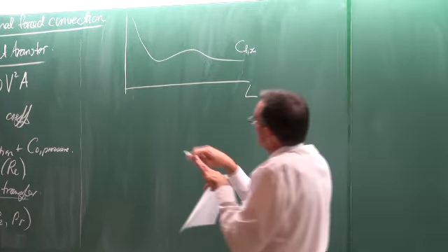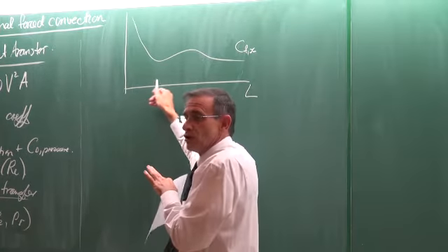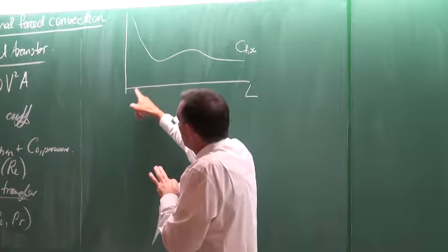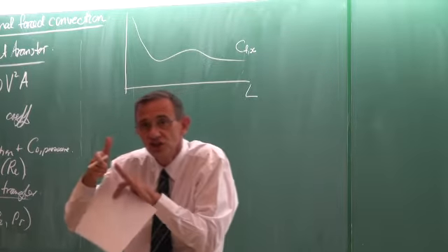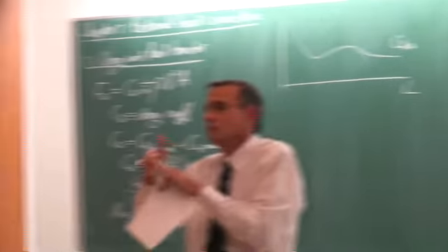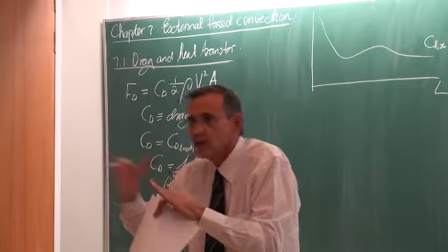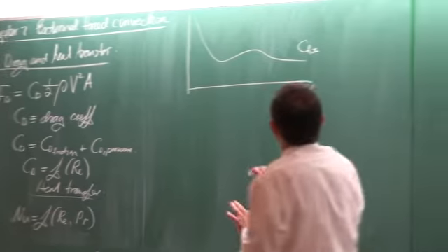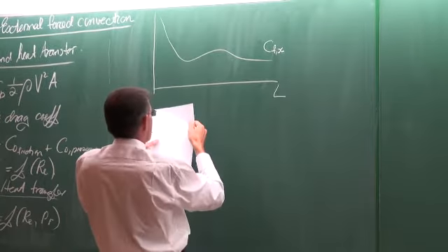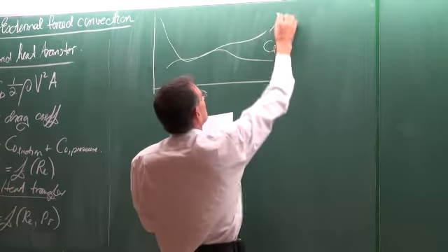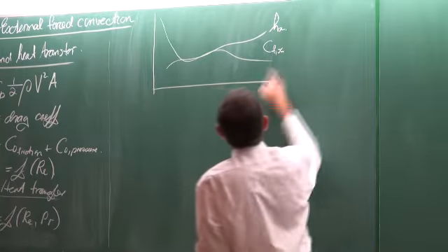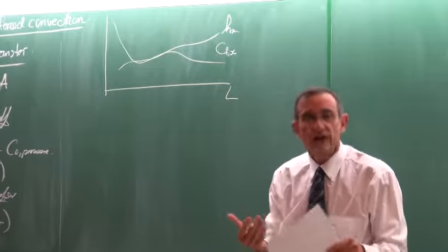Okay. If it's a flat plate and we do measurements on the flat plate, then it would differ from position to position because of the boundary layer, the velocity boundary layer as it develops. Okay. And the same with the Nusselt number or the heat transfer coefficient. Okay. So they are actually local values.